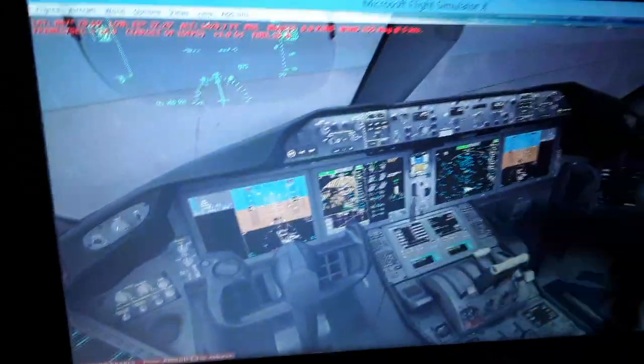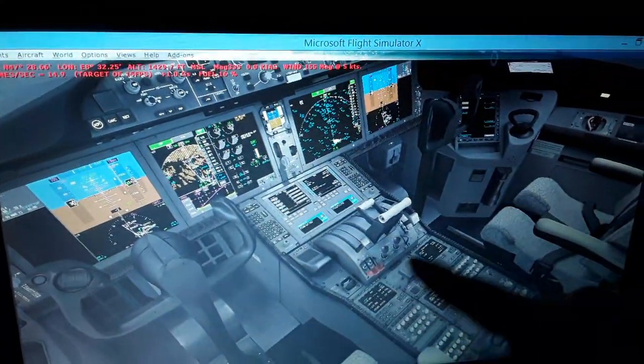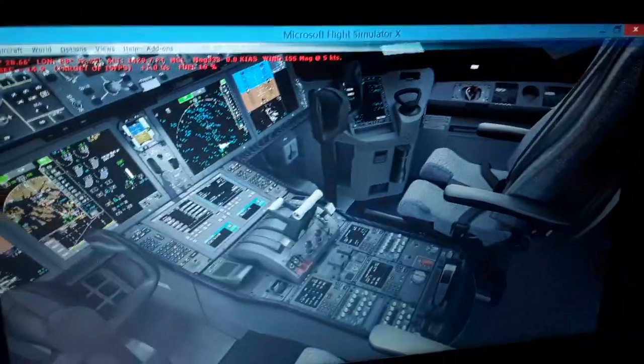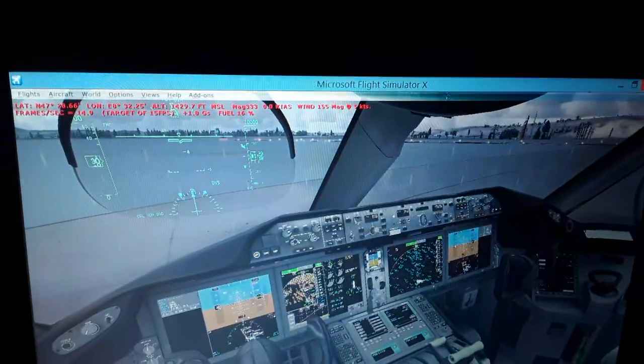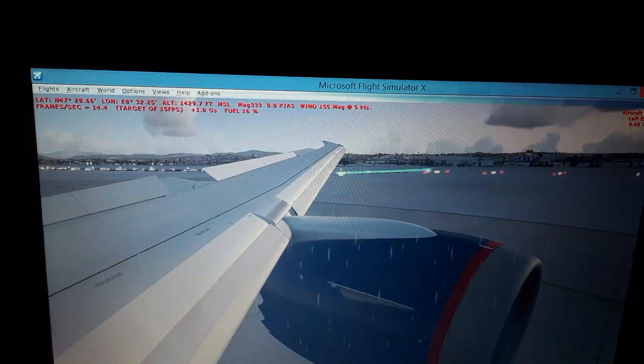So we're going to use the magnetic heading for this flight, 136 degrees for runway 14 at Zurich International Airport, LSZH. So we're going to have a complete flight plan or flight path or route for this flight. Also, we can tune the LSZH localizer automatically from the flight management computer, or manually using the radio management panel here, the communication and the navigation displays of the radio management panel.